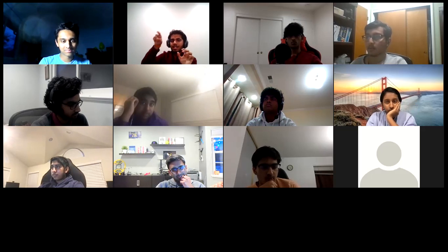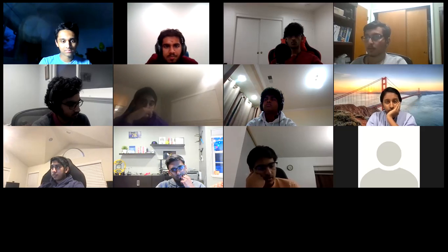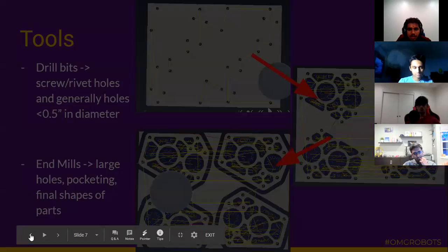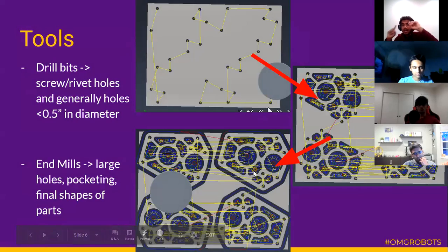The reason for that is, if you cut out the outline, let me actually share the slide and go back to the picture. When you cut out, and you've seen the third picture, the bottom one, when you cut out the outline, this middle piece no longer has any aluminum supporting it, right? So you're doing the same thing for the bearing hole, except in the middle of the bearing hole, there's going to be what's called a puck. It's a super small piece of metal that was left over because you only did the outline. And now that piece can fly somewhere, basically.